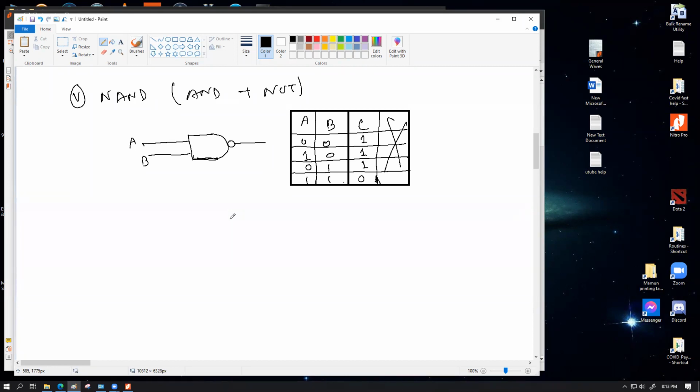Okay? Now compare the shape of G1 with the shapes above; you might not have memorized them yet, but compare the shape. What type of gate is G1? What gate would you call this? AND gate. It's an AND gate, which means it will give you 1 only if both the inputs are 1. So for the first row, x and y both are 0. So the G1 gate will give us an output of 0. So in this place of A, write 0. You can write on your book, but use a pencil so that if you're mistaken, you can erase this. You can write 0 over here.